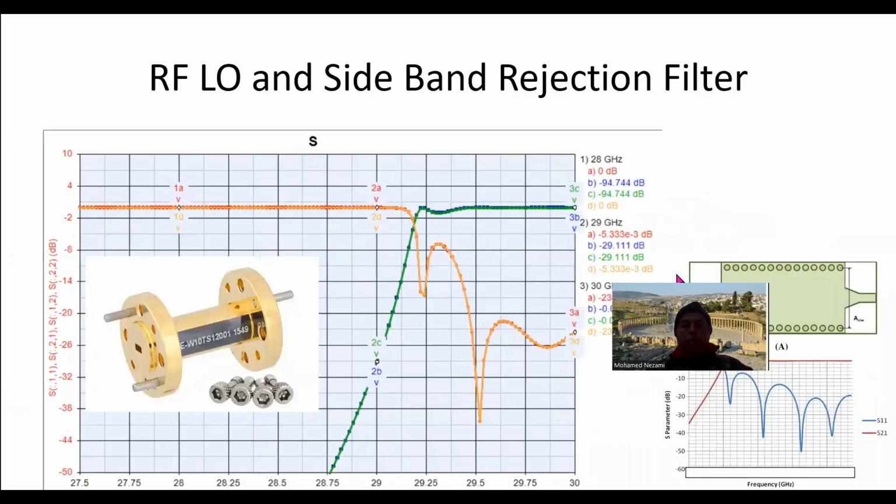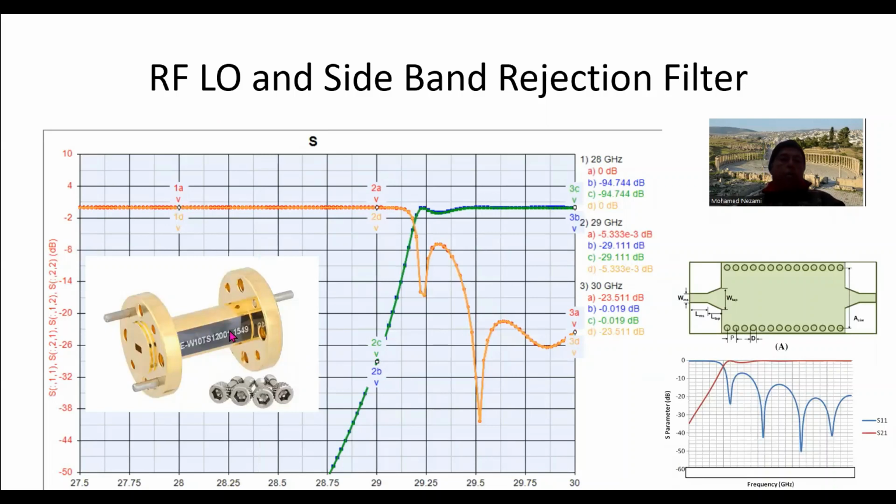So, finishing the IF: the filtering of the sideband, I did it using a little section of a waveguide. And the way to do this is you basically have a cutout in the board, and you could design it using waveguide to PCB to microstrip transitions and have a waveguide that gets assembled to your board. But my objective in this is I'm going to go out of the board to the edge of the board to have an SMA connector in there, and then come back again at a physical distance that is long enough so that I can use an externally connectorized waveguide section, a small section.